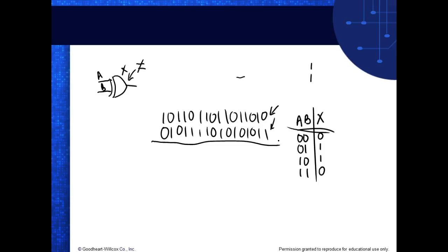So if I do it with contacts, I'm going to be working on 2 bits. But if I do it with words, I'm going to be working on 16 bits at a time. And where can those words come from? Well, those words could come from 2 16-bit inputs. We would have to look and see how Siemens does this. Siemens inputs are set up in groups of 8, and Allen Bradley's are set up in groups of 16, right? So Siemens does bytes, and then they might do words. I need to look that up, like I said, I'm learning that myself.